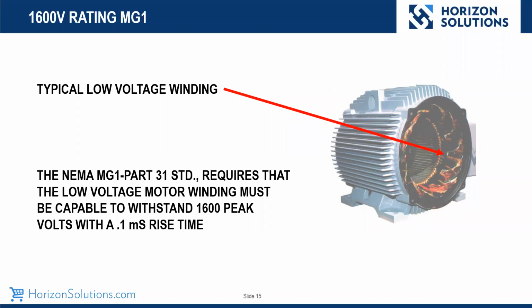Nominal peaks that you see are usually about 3.1 times the 480 volts that is being introduced onto the drive. Also, this comes into play with the short rise times. You're down at 0.1 microseconds for rise times with these IGBTs. Next slide.